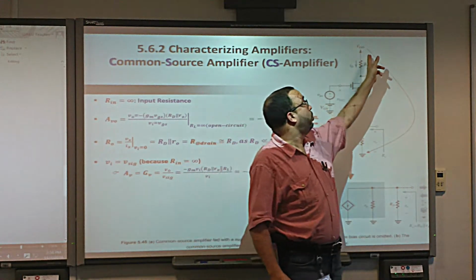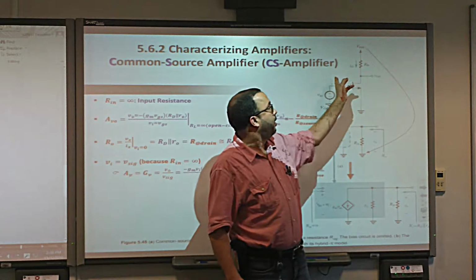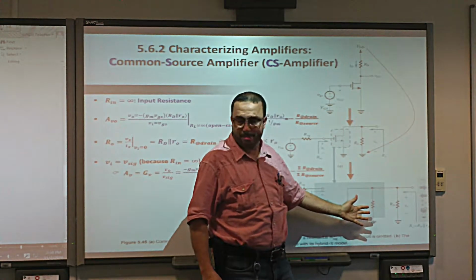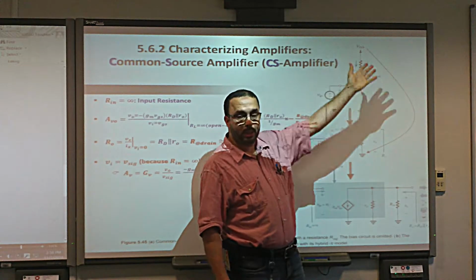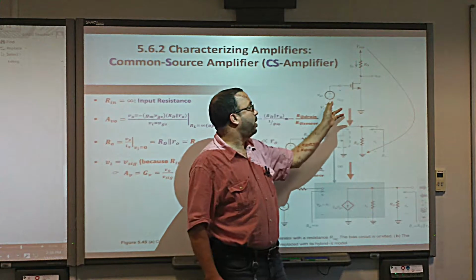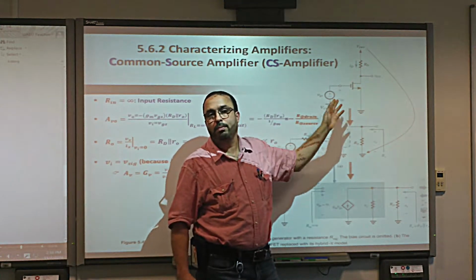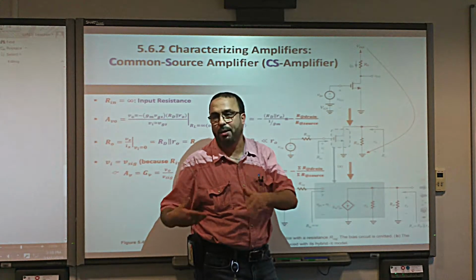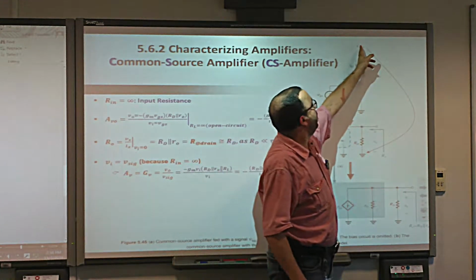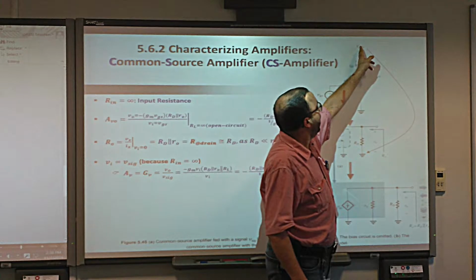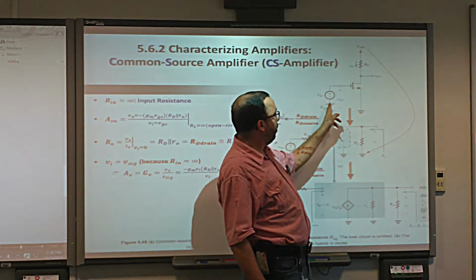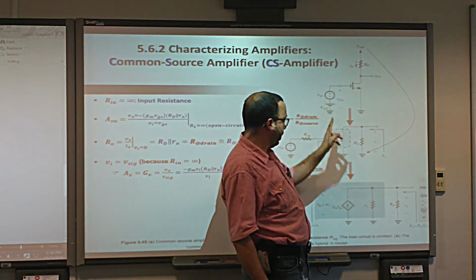So the first step is to convert the circuit from the DC domain to the AC domain. And we do it step by step. So all DC voltages, they become what? 0. Because we are talking about variation. It's like we are deriving them, derivative, okay? Because we are talking about AC. So this constant voltage, DC, it becomes 0. This, it becomes also 0. That means there is a short circuit here.